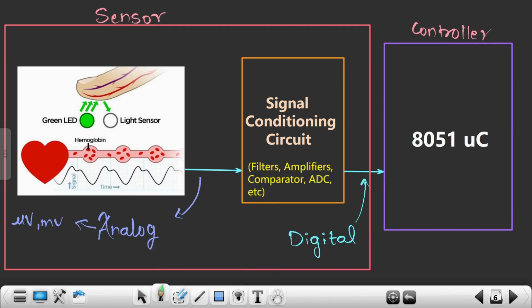So at the output of this sensor, somewhere over here I should get a digital signal which should move from low to high. That means it should move from 0 to 1. Why 0 to 1? Because we had clearly seen that during this interval we will get 0, and during this interval we will get 1. So something like this, 0 and 1, 0 and 1. I hope this color is visible to you all.